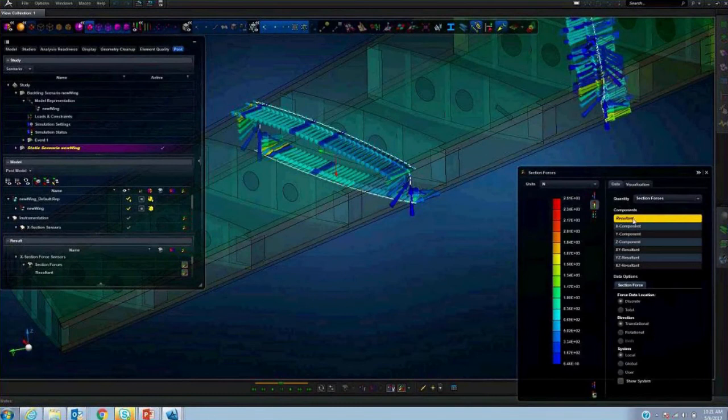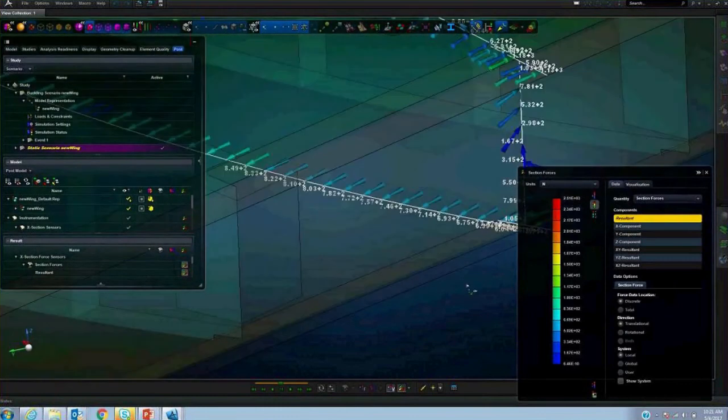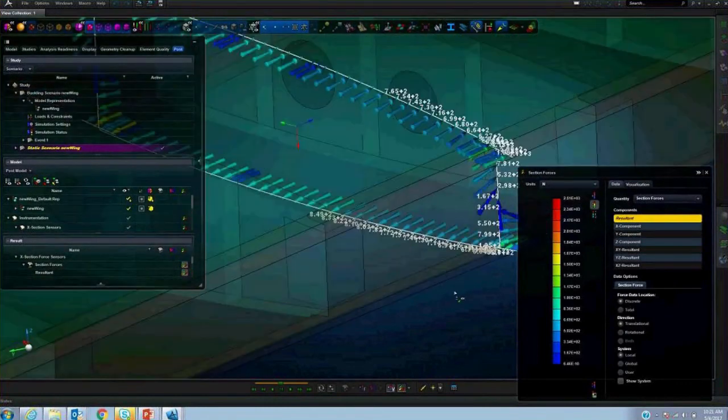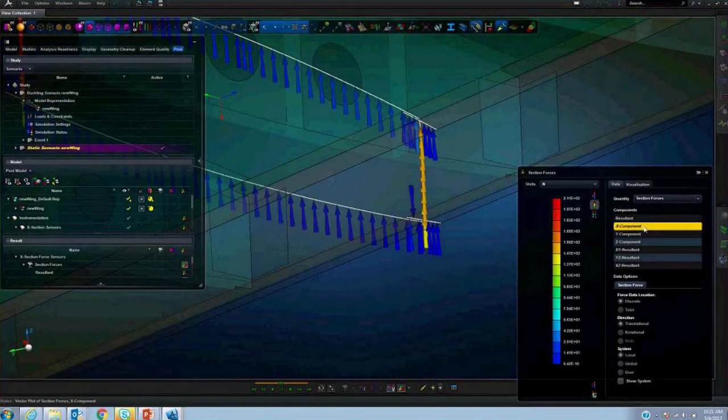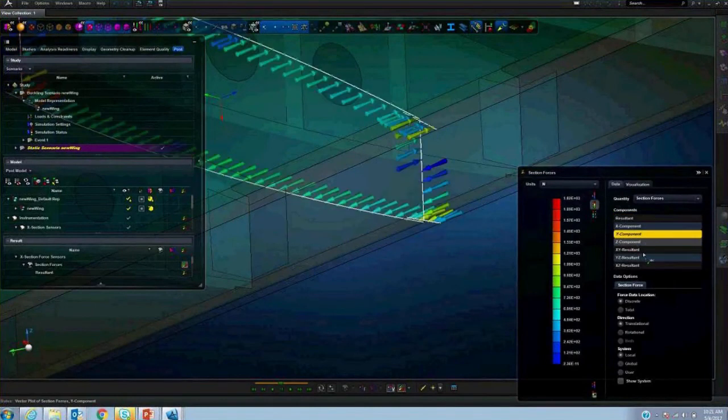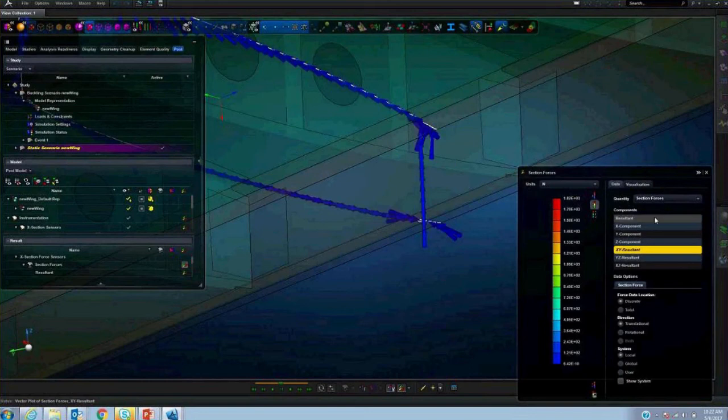And now if you draw a box around those, it will show you the cross-section forces of the contribution of all those cut elements along the cutting plane. And you can also look at the different components, for example, X component, Y, Z, XY, etc. And all these you can look at either in the local coordinate system of the cutting plane or global.